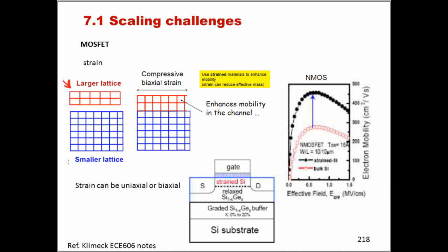In order to modify the effective mass of the carriers, and so to strain the material effectively, what we do is put our original material, generally as a very thin film, on a bulk piece of material that has a smaller lattice.